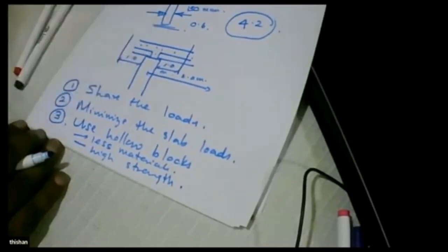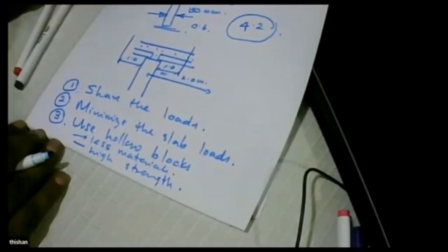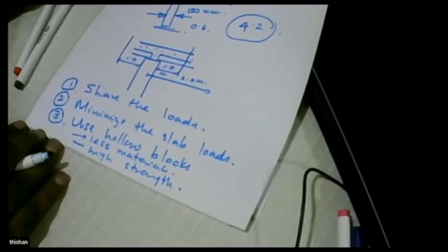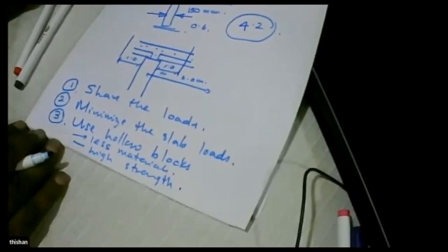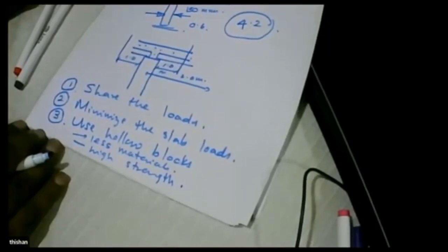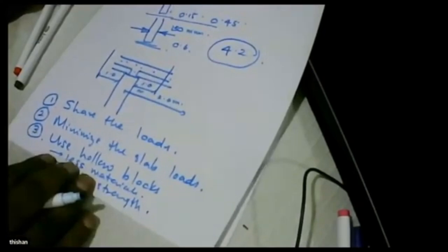So basically, you can see there's no risk even up to 4 floors, though the wall thickness is only 150, and you can support this lightweight system up to 4 floors. So any apartment building having up to 4 floors, this method may be feasible, because our idea is to minimize the amount of concrete in the slabs, minimize the amount of material in the structure.